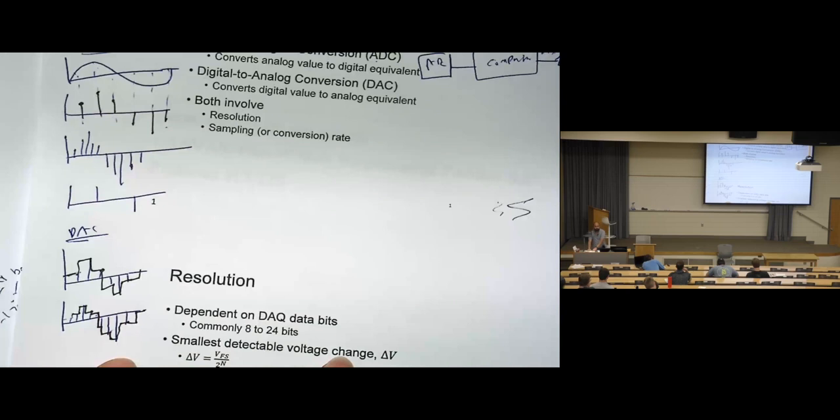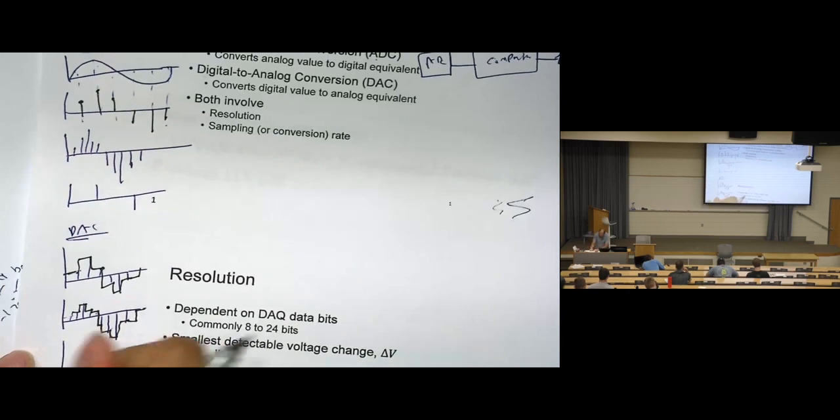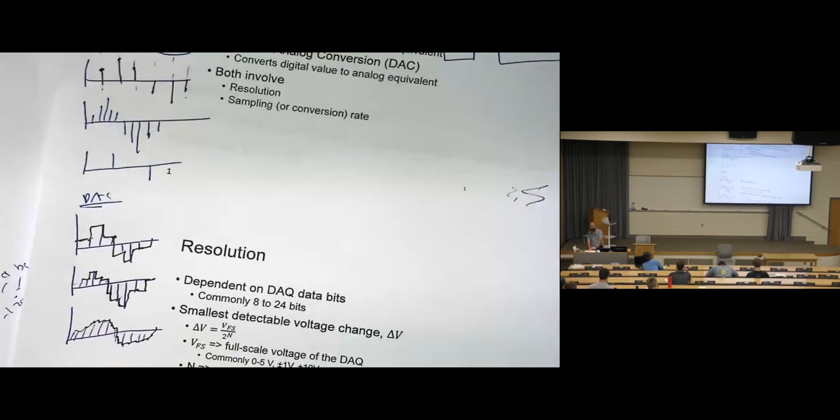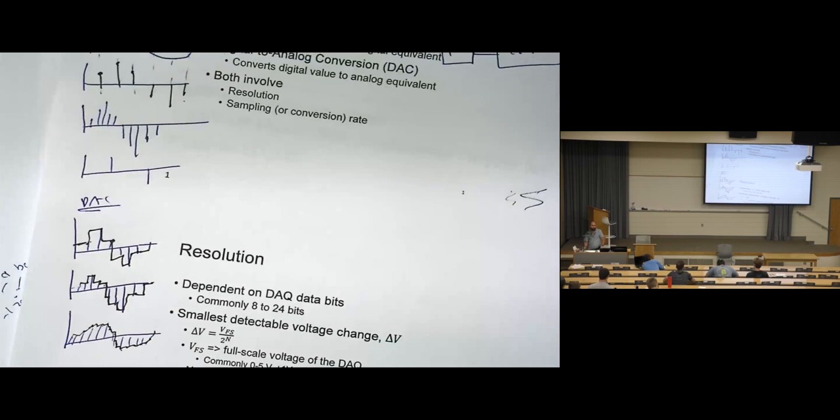This one is better, but still not a sinusoid. How about if I increase it more and more? So we'll get something also very similar, very near to this. So as much as we increase the sampling rate, or the number of samples, the more similar the signal will be to the original, and the less information we will lose.